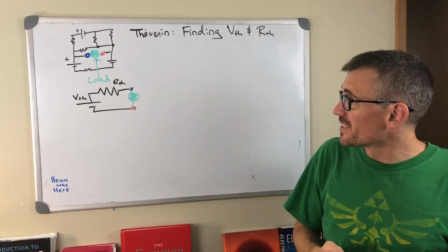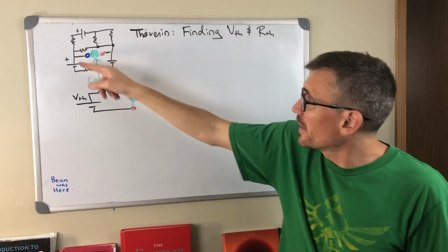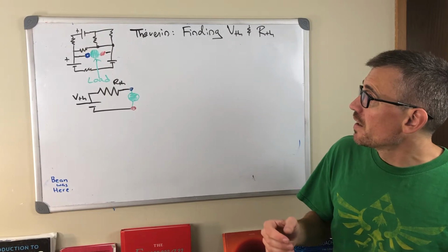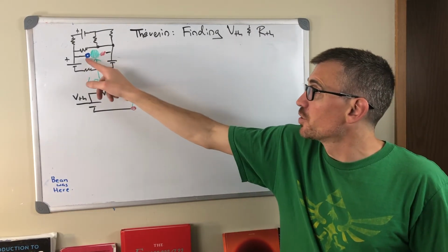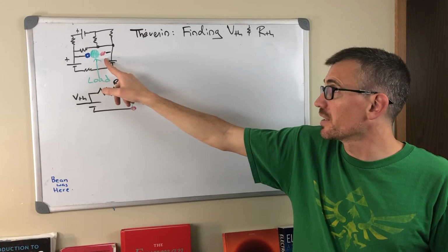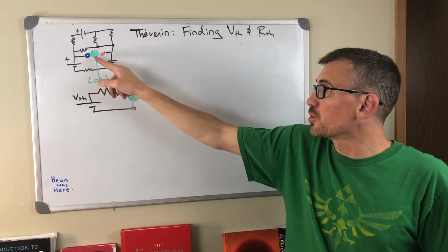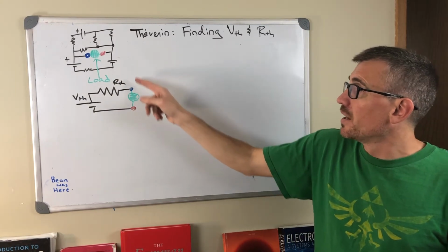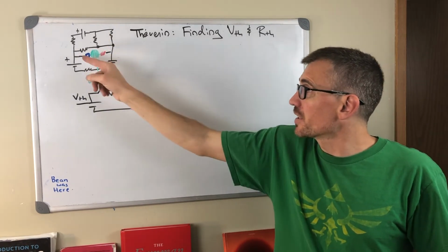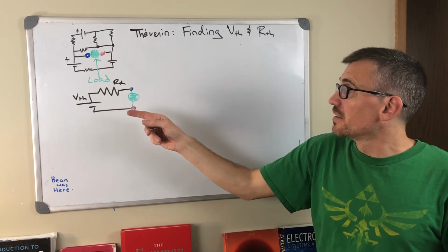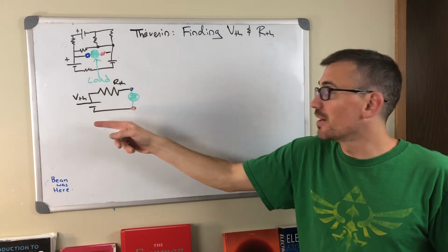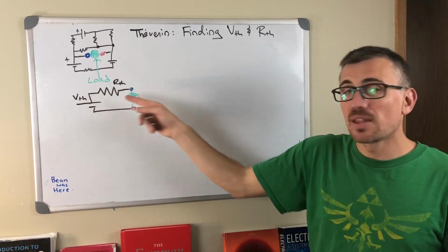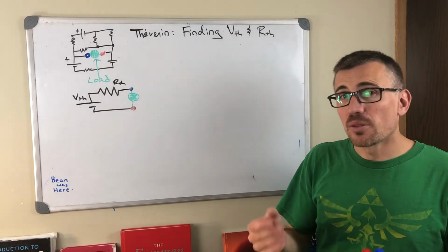Thevenin's theorem told us that if we had any complicated nest of linear circuit elements, I can look at between 2 points here, 2 terminals, say the blue and the red point on this circuit, and whatever load is put there, we can put as an abstract load, and the action of the rest of the circuit on this load is equivalent to a real voltage source, namely a V-Thevenin, or ideal voltage, in series with an output impedance, R-Thevenin.